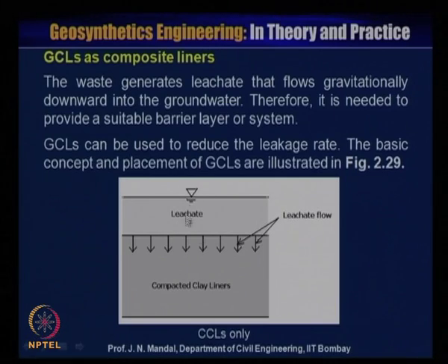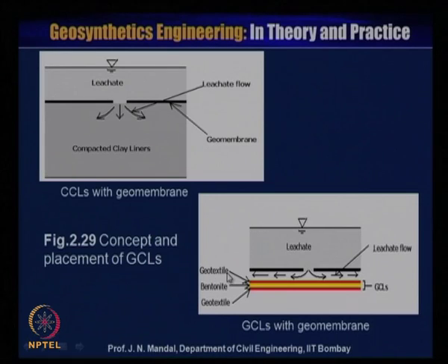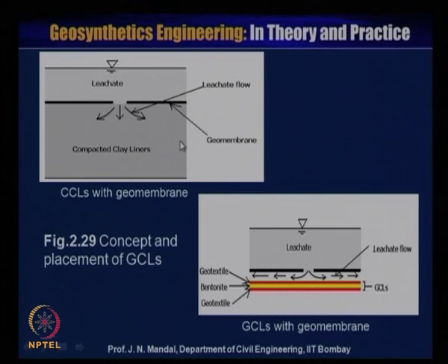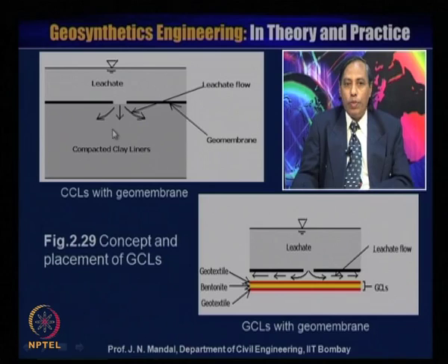You can see the leachate formation in the landfill. The leachate can flow even if we provide a compacted clay liner, which is the traditional method, and you can see how the leakage can flow even then. In the case of a geomembrane material with a hole, the leachate can pass through it and flow. So, how does the leachate flow here?